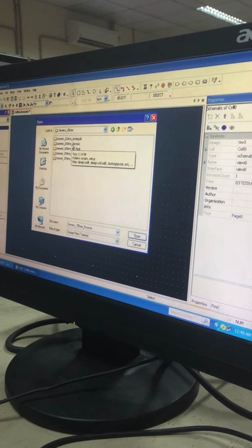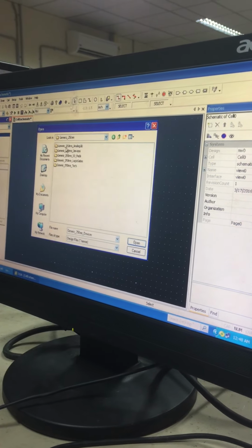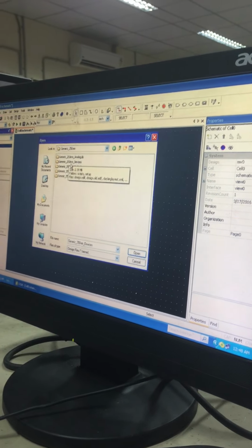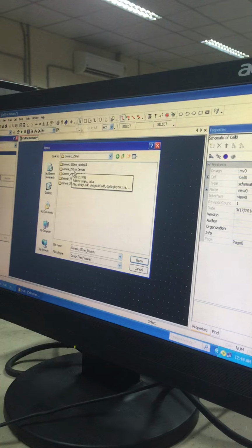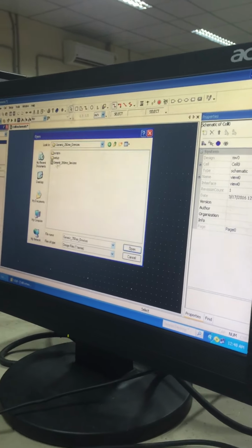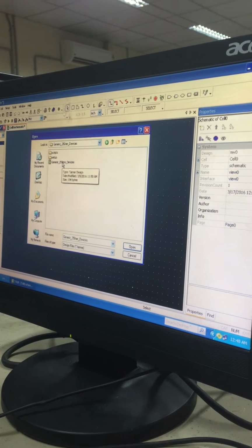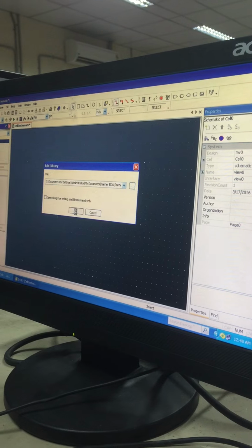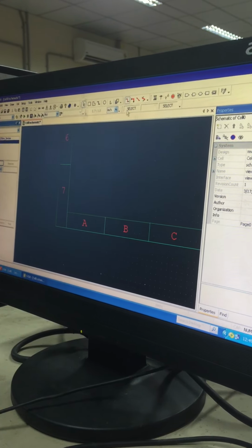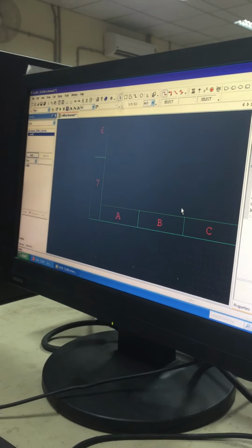You have generic 250 nanometer devices. Generic 250 nanometer is the technology which we use here. It represents the width or size of a circuit component. Under the same name, you will have another file. You have to double click on it and click OK. So it will get added here. Now this will define the boundary within which you are going to construct your circuit.